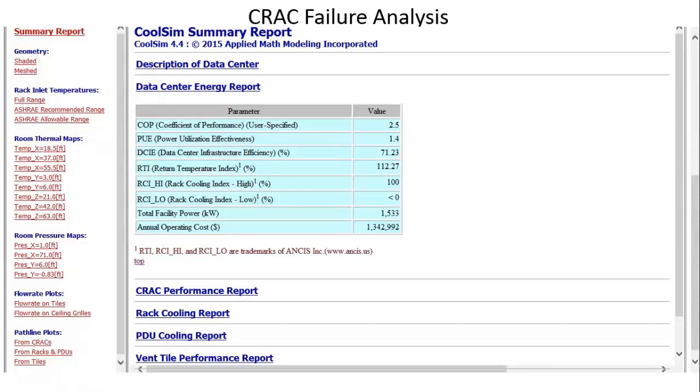So if the air can't come from the cooling units because it's simply unable to deliver it, or it can't be delivered efficiently to the right location, then the only opportunity it has is to wrap the air around the server itself in some way and feed it back into the intake, or stall the fan inside the server, which would be pretty much the kiss of death for a server. If it's got no airflow, it's going to go hot quick.